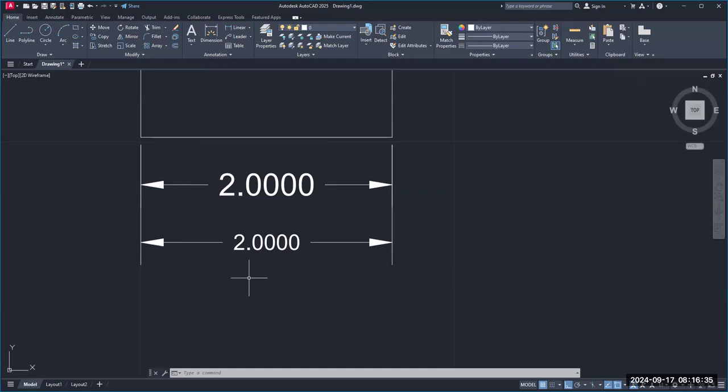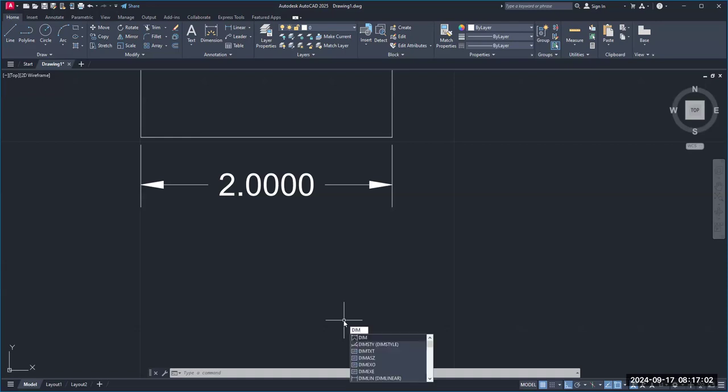What I have noticed, it seems to work pretty good. Whatever your text size is, you should make your arrow size the same. What do you mean, Mr. Morris? Well, I'm going to erase this. I'm going to click on this and just hit the delete button. Now, so I taught the first command, DIM-TXT. And by the way, there's other ways to do this. I'm just kind of showing you the hard way right now. I'm going to type in DIMASZ.